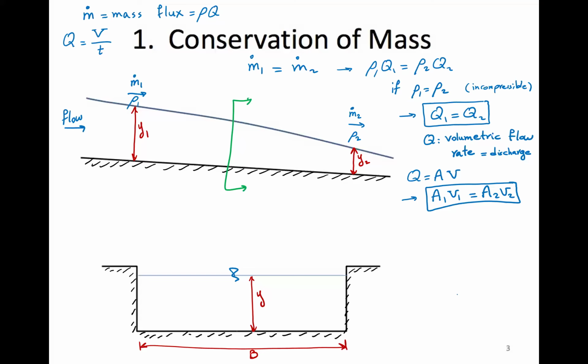All right. So let's look at this from the section standpoint. We have discharge at section 1 equal to discharge at section 2. By the way, it's obvious, but we are assuming that there is no change in channel geometry from 1 to 2. Everything is the same, except for flow properties like velocity, area and depth potentially. But the geometry is not changing. We will look at that later on, but for now, we're going to assume that the geometry is the same. So Q1 equals Q2, which means A1 V1 is equal to A2 V2, nothing new.